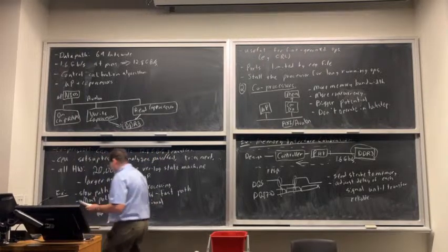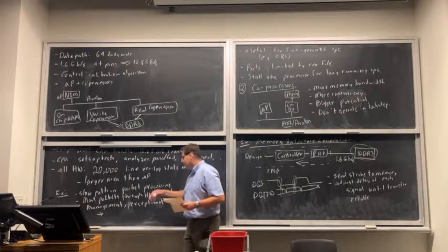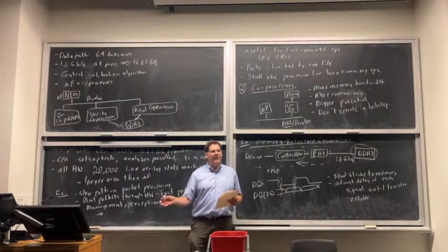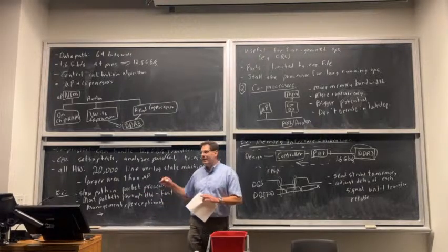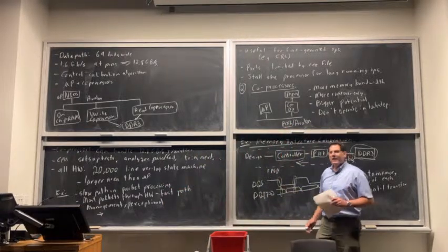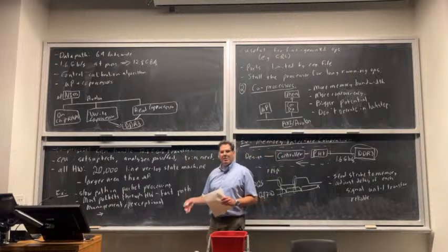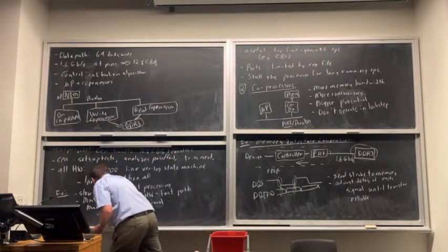So for these ones, the slow path is often written in software. So the hardware just detects, oh, based on this pattern, this is actually one of those weird packets. Nobody coded that in my pipeline. Send it over the bus to a microprocessor, and it's going to process it. It might be 100 times slower than me, but as long as there aren't too many of these packets, it's fine. Okay? So you do the slow path in software.